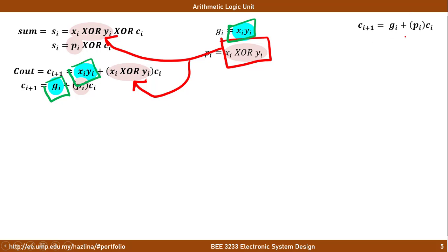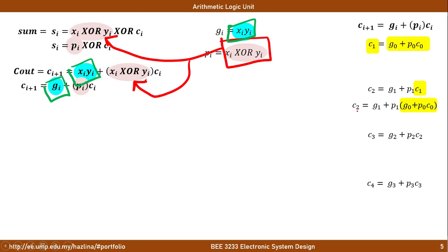So for the first addition cycle, we can do the prediction by having this item. So Ci is the carry in for the first bit, for the second cycle, for the third cycle, and for the fourth cycle. Okay. So the properties of Ci here, which is equivalent to G, the generation bit at 0th level, and the propagation bit at 0th level, can be simplified into this equation. Likewise, C2 here can be simplified into this version, as well as C3 here can be simplified into this version.